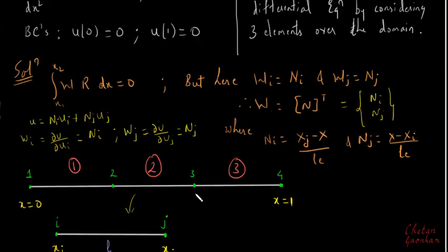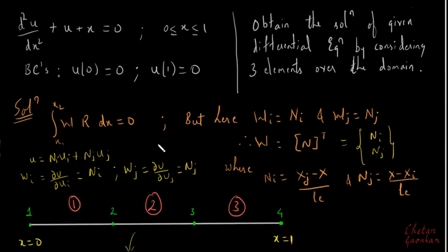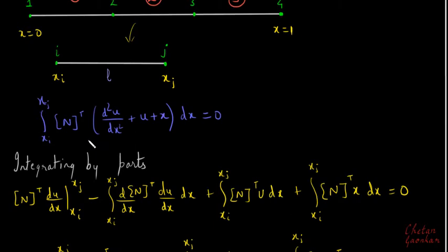And we know that whenever we use Galerkin's weak formulation, it is the modified Galerkin method, and in that case, even before substituting the trial function, we integrate the weighting function multiplied by the first term of the residual by parts, so that we manage to reduce the order of this term. And exactly what happens here, after integrating by parts, we get this,